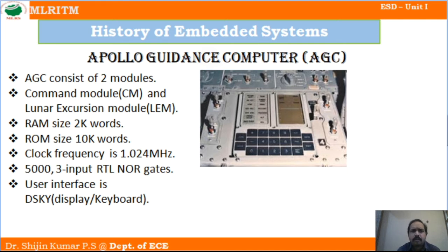The clock frequency was 1.024 megahertz. As I told you, at that time we didn't use any ICs. We used 5000 3-input RTL logic NOR gates for the development of this computer.